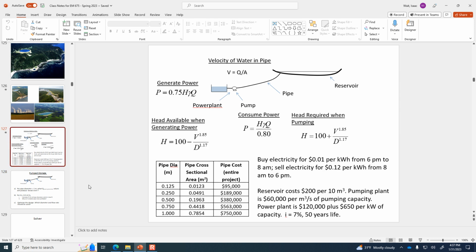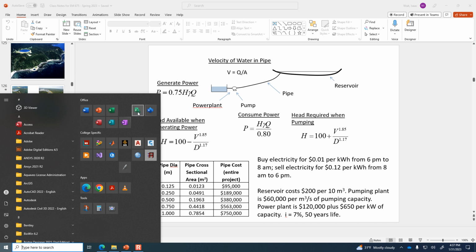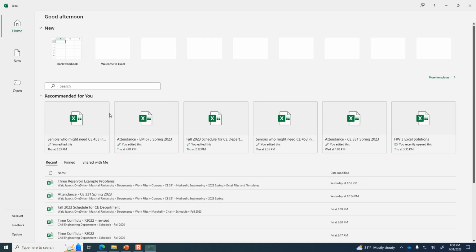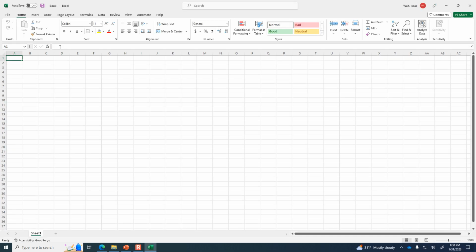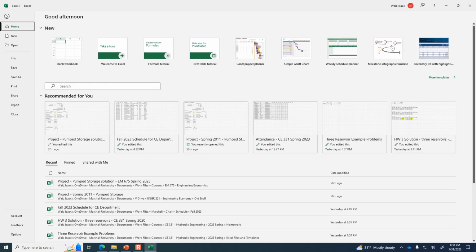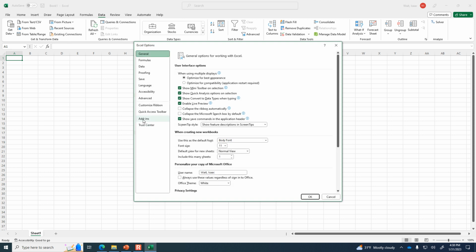All right. Well, let me just give you a hint of where this is all headed and show you a tool in Excel called Solver. Solver isn't turned on by default, so the first thing I'm going to do is show you how to get access to it, because if you open up Excel and go to the Data tab, you may not see Solver over here on the far right, because by default I think the Solver is turned off. And it's here in the options, I think, add-ins.